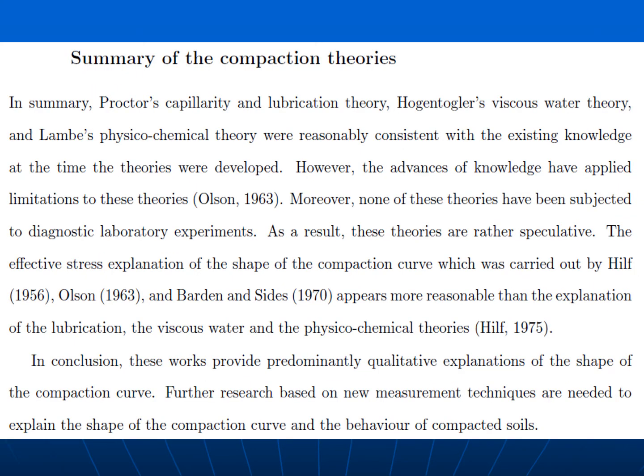So in this way we focused on different theories, and here you have a summary of those compaction theories. Let's see it. In summary, Proctor's capillarity and lubrication theory, Hogentogler's viscous water theory, and Lambe's physicochemical theory were reasonably consistent with the existing knowledge at the time the theories were developed. However, advances in knowledge have applied limitations to these theories.